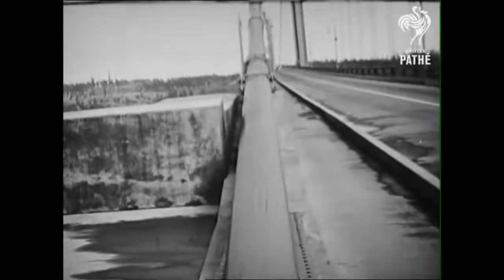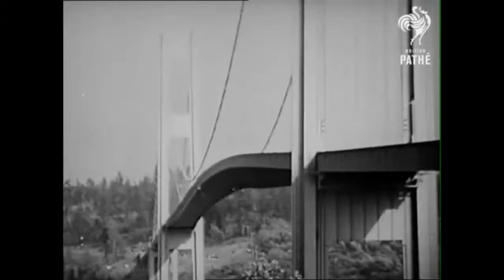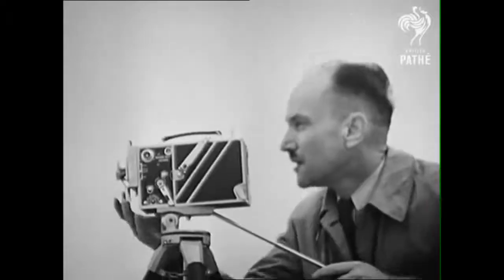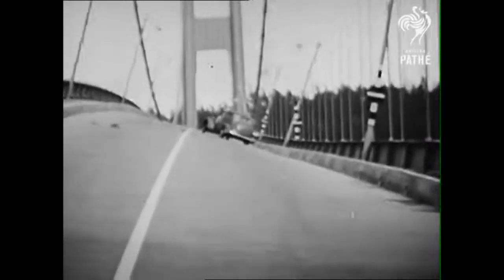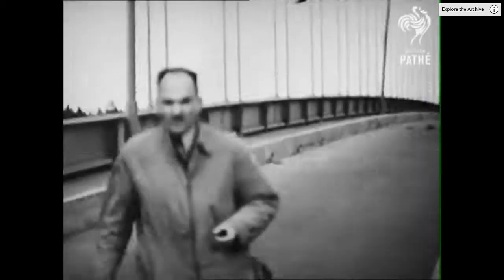So this is a resonance frequency load. The wind is traveling over the bridge, and it's just been designed in a way that... mile-an-hour wind is blowing, but this apparently sets up a rhythmic swinging of the bridge, which increases with each swing. And so that particular live load wasn't considered in the design, and you end up with catastrophic failure.